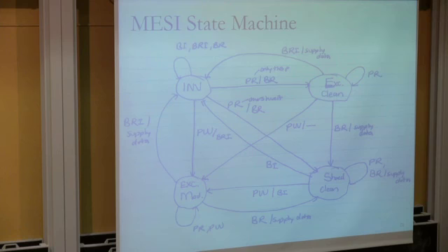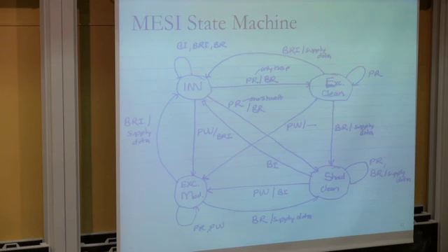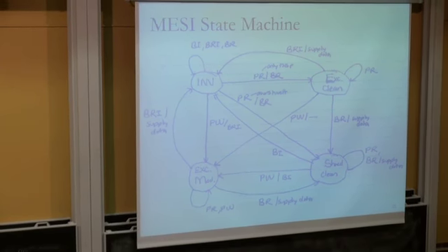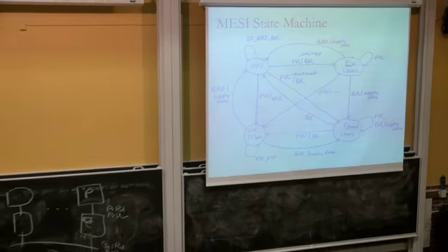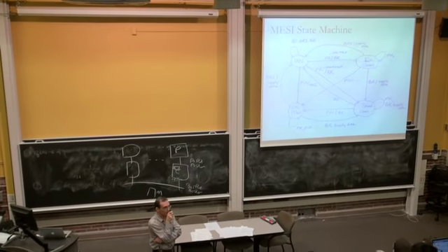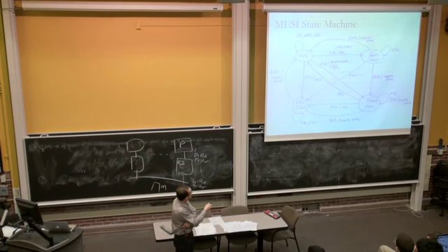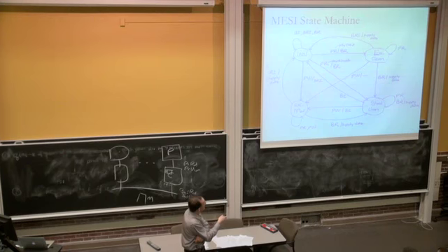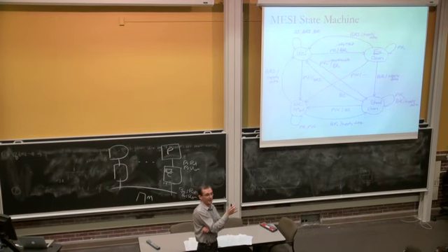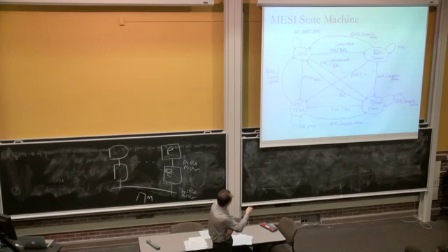Yes? Would another advantage of having the exclusive state be that when you evict a block, you might not necessarily need to propagate the write to the lower level, because if it's clean, then you don't need to change it? Well, if the block is clean, you don't need to write it back anyway, right? If you actually wrote to it, then you go into the modified state.